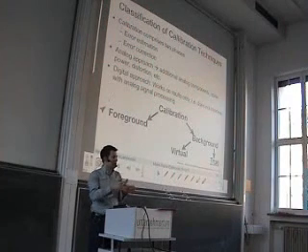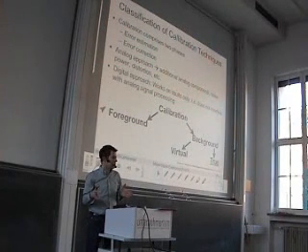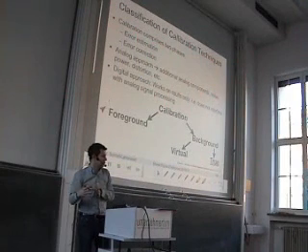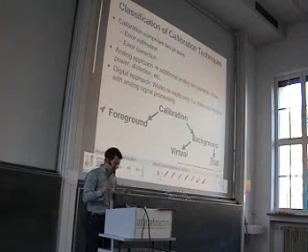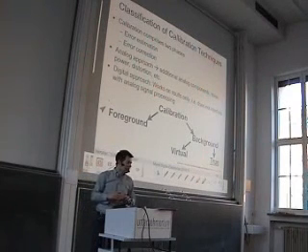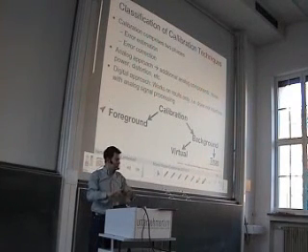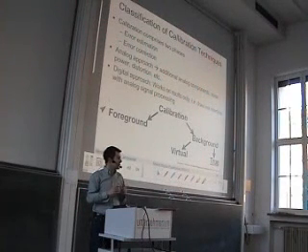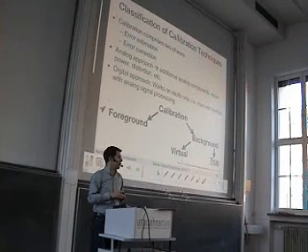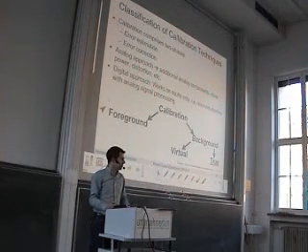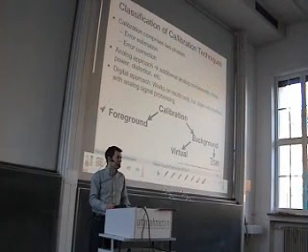So if something happens during your operation of the system, the background calibration adjusts this and compensates for it. There are also two ways. The true background calibration is the one I showed you, which uses the actual hardware and runs in a tricky way that does not interfere with the normal operation, for instance, using noise, which is then extracted by correlation.